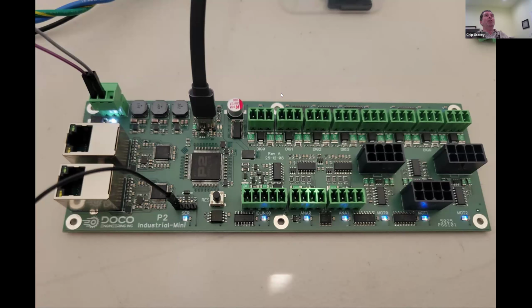You can have ongoing miswiring errors that could completely wreck stuff if you didn't watch out. So you see these green parts here, these are PTC resettable fuses, positive temperature coefficient. When they conduct enough current, they get hot enough that they open up. There's a carbon compound inside, almost like graphene or graphite.